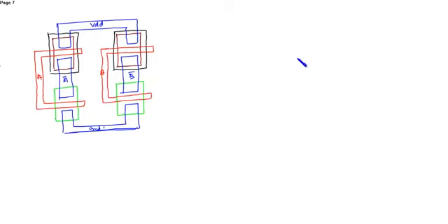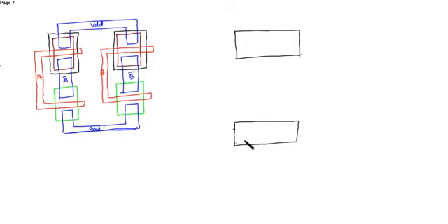Then we have the two transmission gates. So the layout of the two transmission gates can be done as this is NMOS 1. Sorry, that is N-well 1. This is N-well 2. Similarly, we need P diffusion 1, P diffusion 2.